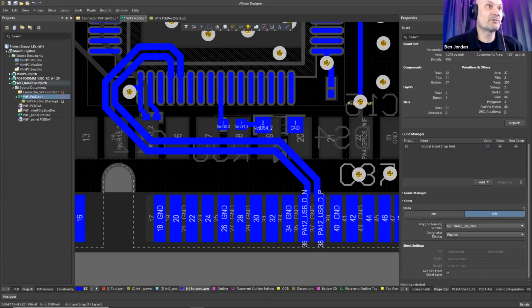You're asking, I have a problem adding _P and _N label numbers for several different signals automatically. For example, I want P1_N and P1_P, P2 and so on, how do I set it automatically? I think what you're saying is you have a bus of differential pairs which are suffixed with different numbers for each bit, and you want to add the _N and _P. At this stage, there's no automatic way to do that.